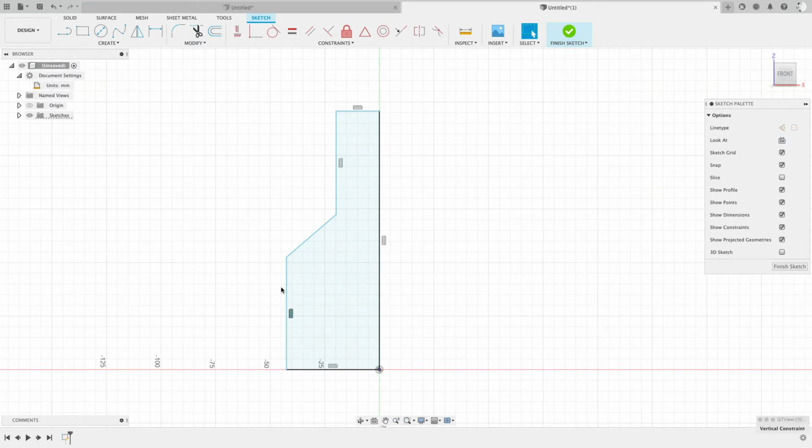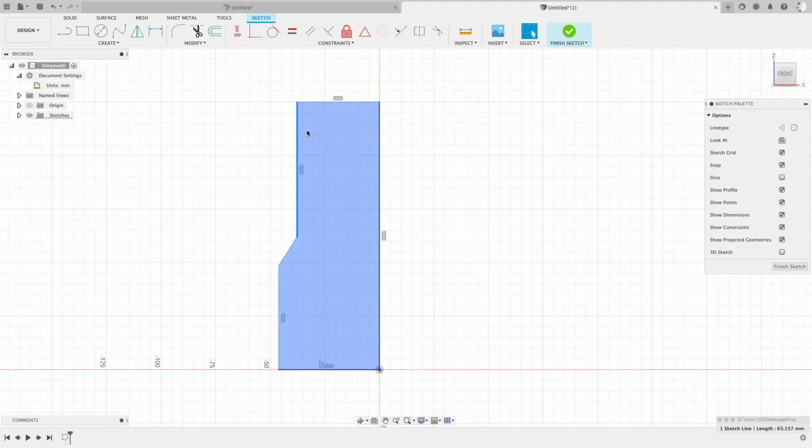this piece. And now the software will think this will be more horizontal, but I want this to be vertical. So you see the software guessed incorrectly. This has to be more vertical. Cool. Okay, escape. Now, when I move this point, you see I can move this point up, but this moves up and then this moves left and right. It doesn't rotate anymore. So that's kind of like, in a nutshell, as a quick introduction, what sketch constraints are doing. These are like rules how all the elements can behave.